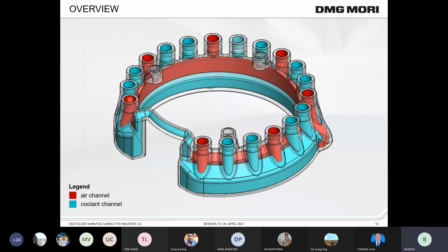We have here a lot of nozzles or sockets for nozzles. And you can decide by designing this breakthrough, is it an air nozzle or is it a coolant nozzle? So in this case, two coolant nozzles for one air nozzle, but it's also possible very easily, by changing the design of our part, to say, hey, I want one air, one coolant, one air, one coolant, or it's also possible to say one air, 5 coolant, then again one air and 5 coolant, and so on.